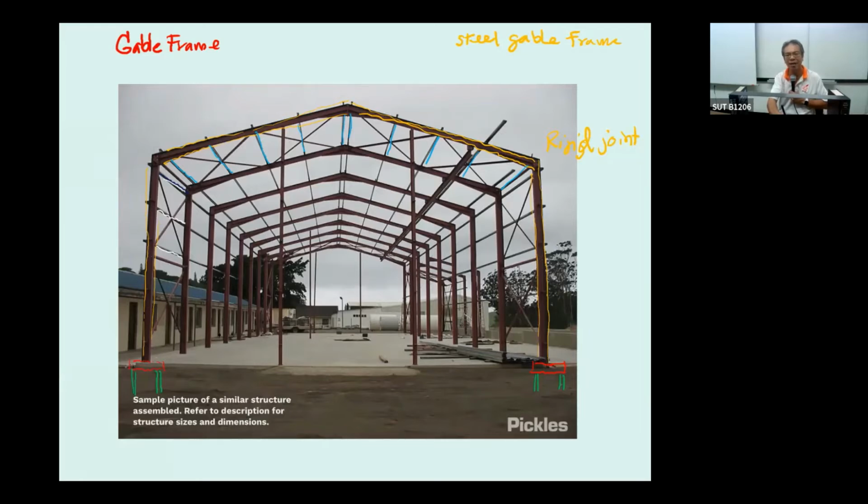And then before finishing this one, you're going to put the tie rod that I just mentioned into this. The tie rod will help to stabilize the structure from the action of the lateral loading.